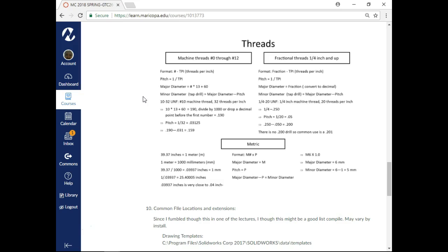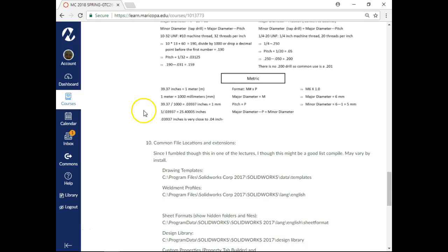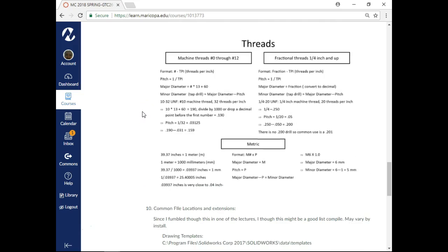I've broken more 3D printed parts thinking that I put enough fill and enough structure into it, only to find out that, yeah, it was really a great prototype, but I still need to make it out of aluminum, out of Delrin, out of poly, whatever. So the threads need to still be incorporated. And I've printed the minor diameters of the thread holes and then gone back and tapped and gotten really good results. So knowing this basic information, having something to start, even if we have to drill it out, is a good way to go.